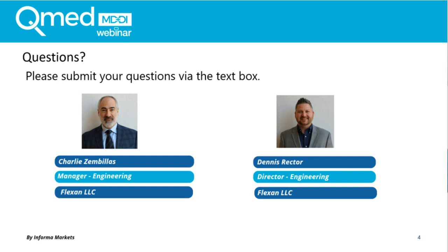All right, thank you, Dennis. Another question asks, what was the name of the treatment you mentioned to improve bonding? There's a couple kinds of treatments you can use, and the ones I mentioned are corona treatment and plasma treatment. Correct, which generally are very similar. Yeah, very similar. They affect the surface energy of the tubing, allowing a bond to take place. They're temporary treatments. They don't last a long time, so if you conduct a corona or plasma treatment, you need to bond very shortly after doing it.